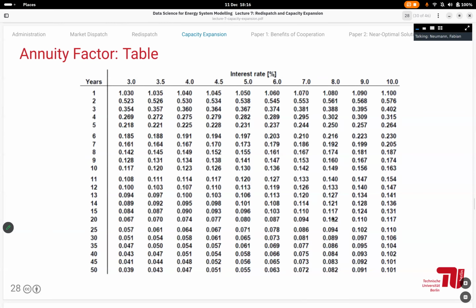So far, I showed that basically all the constraints we have in the system are the same. There are a few additions that you would typically see in capacity expansion problems. I'll get to that in a moment. But the more basic thing is that for your investment variables, you would also see limits themselves. The investment capacities limit the dispatch, but the capacities themselves might be limited by the land eligibility calculation that we did at some point. Maybe it's limited how much wind you can build in a certain region.